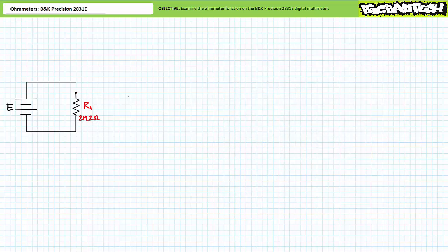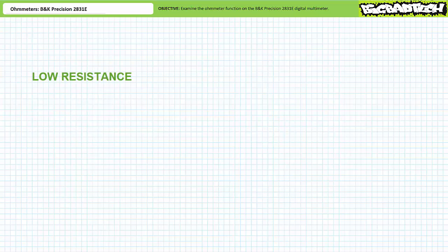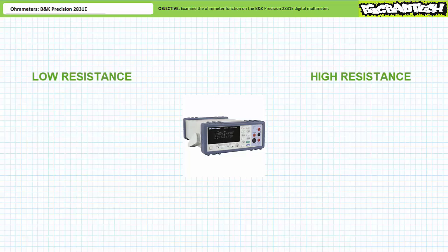Before we bring this lecture to a close, let's talk about the lower and upper extremes of resistance measurement. At the low end of the resistance spectrum, consider a length of thick, highly conductive cable. At the high end of the resistance spectrum, consider the rubber or plastic coating of insulation surrounding a wire. Regarding measurement of these two low resistance and high resistance extremes, do you think any measurement obtained using an ordinary DMM would be accurate? Not even remotely. If you required exact measurements of such small or such large resistance magnitudes, one would have to use special equipment purposely designed to measure this level of detail.